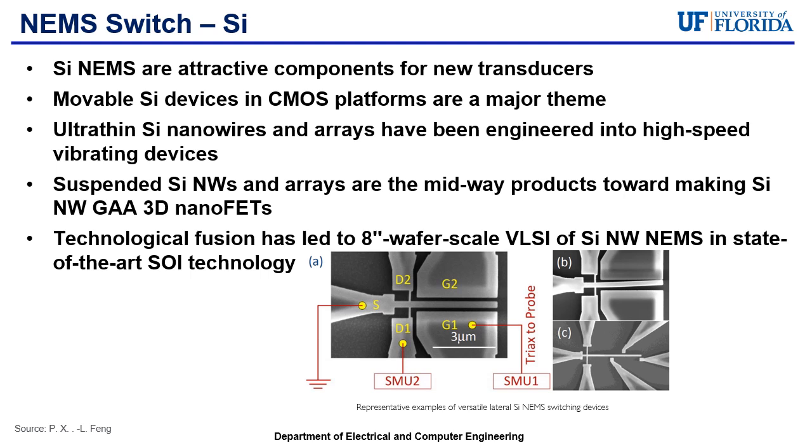One significant trend in silicon NEMS technology is the integration of movable silicon devices within CMOS platforms. By combining mechanical functionality with CMOS electronics, we can create powerful and highly integrated systems. This integration not only enhances performance, but also reduces power consumption and improves overall device reliability.